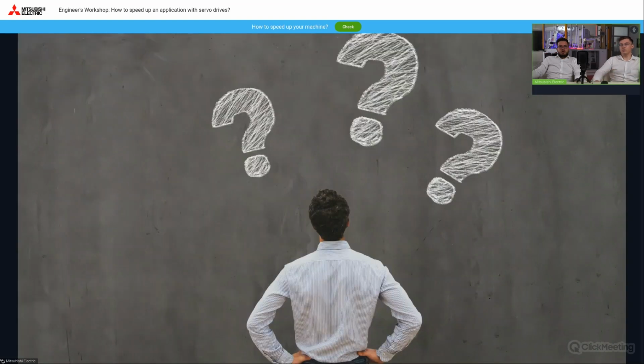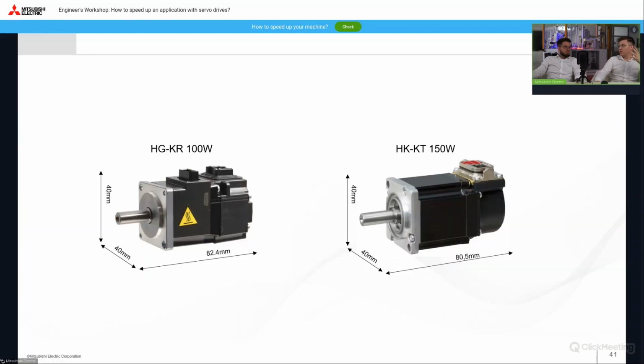All right, but what if we can't use the overload capacity or the torque increase because the mean square torque is above the nominal value? Then you can use the size of the motors. The size of motors? Yes, because usually accelerating a machine will involve increasing the power of the motors, assuming the originally installed ones are not oversized.